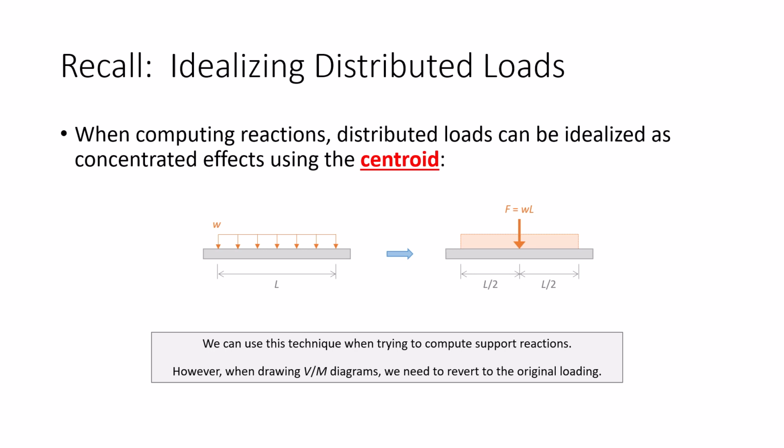What's worse, putting 200 pounds right in the middle or spreading it out? Obviously, lumping all that load right in the middle is going to be a little bit harder on the table than spreading it out, right? You got to convert back to the original loads in order to properly construct the shear and moment diagrams. Does that make sense? You will over-predict moment and whatnot if you do not revert back.